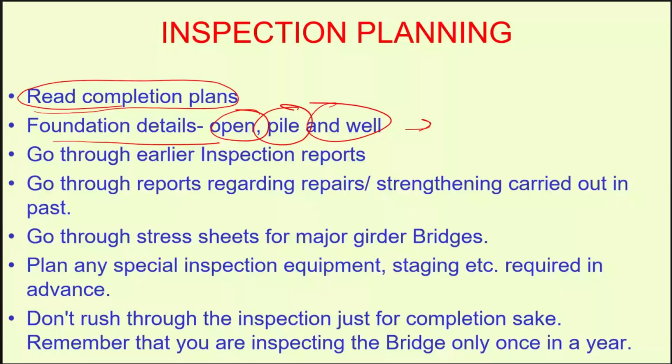Don't rush to the inspection just for the sake of completion. Inspection of a bridge is very thorough and important work. It has to be done thoroughly and religiously. Every aspect needs to be seen thoroughly, and only then do we prepare the report and see what action is required to be taken, and by whom. Because as an officer, the bridge is inspected once, immediately after monsoon. So it is a once-in-a-year exercise. You will come back after a year.